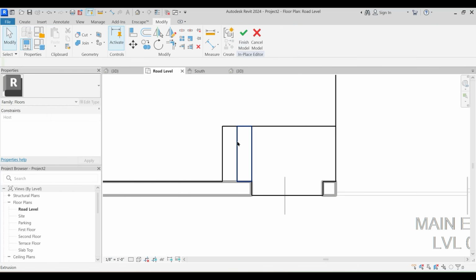Okay, WA, and internal wall from parking till slab top, and pick lines. Oh, I should have selected this tool first. So parking till slab top, and just pick this, flip the direction, TR, and join this to this. Let's see it in 3D. Yeah, fine. So the lift shaft has been created. I'll select this entire chunk, DM, that is mirror, and mirrored. Okay, fine.